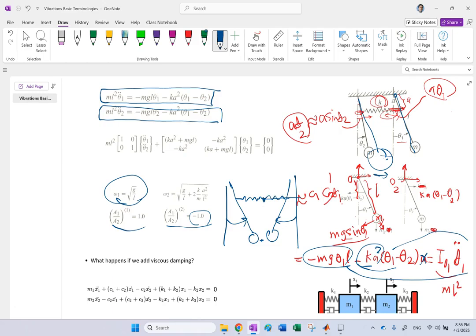That is going to be a point that does not move. So in the second mode, the spring is going to be compressed when they come like this, and when they move to the other side, so this goes here, this goes there, then the spring will be stretched. But regardless of the spring being stretched or compressed, the point in the middle will not move. It is going to stay there, and it is going to be called a node.